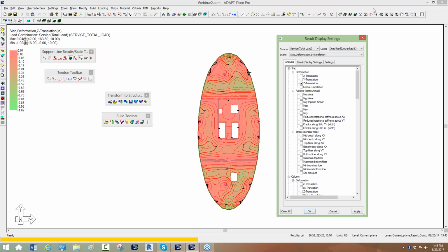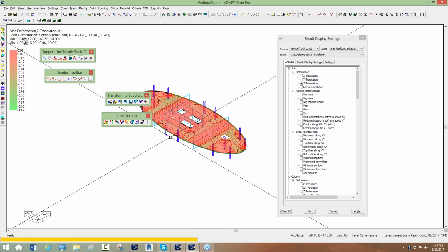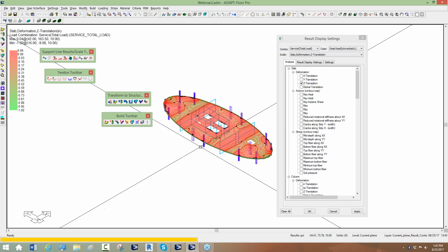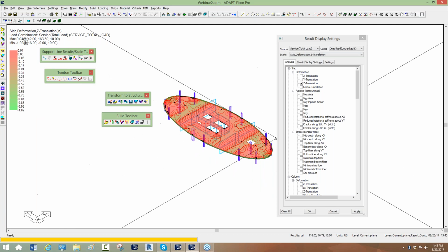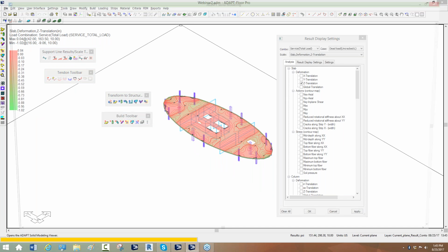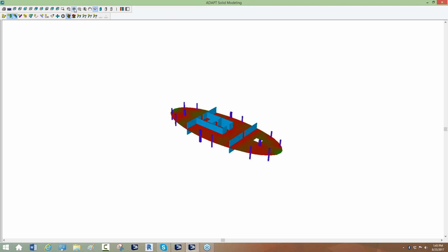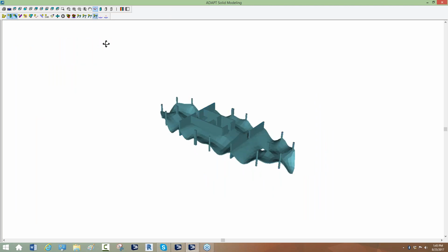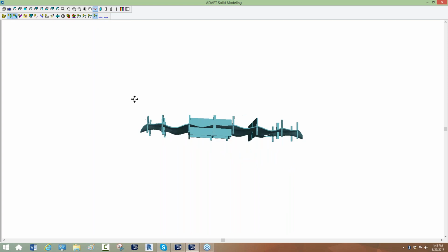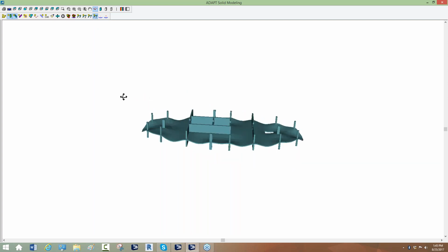This particular view doesn't really tell me the whole story because I can't warp the view in this main interface. If I turn on the result for deflection here, I can go into my results viewer now, and in my results viewer I have the capability now of showing the deformed state of the slab, for example, something like this, and I'll just make sure that's not as exaggerated. And you can see this is just a quick view to see if there's any disconnectivity between components.